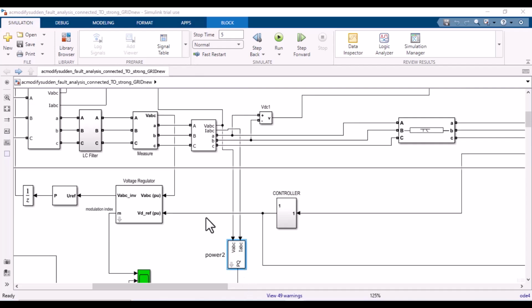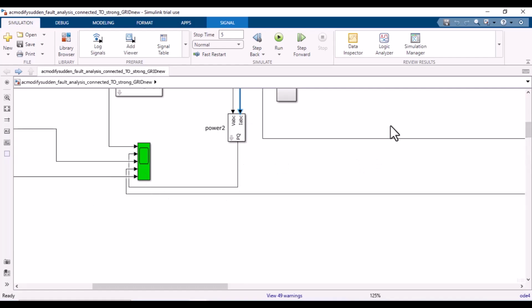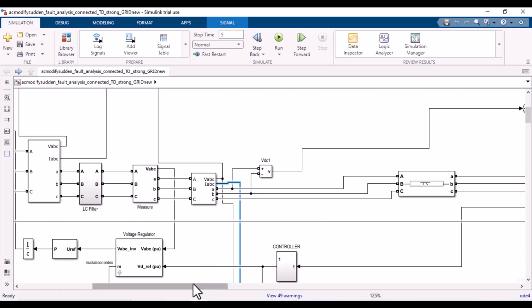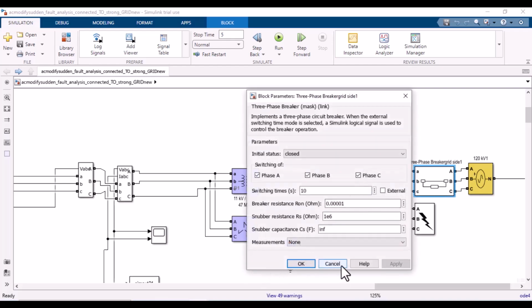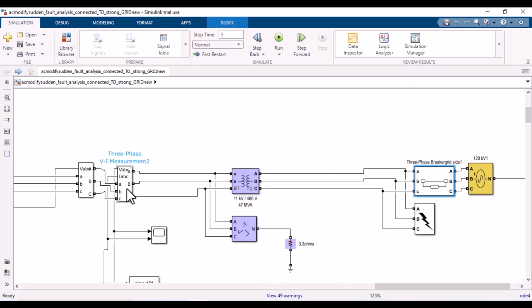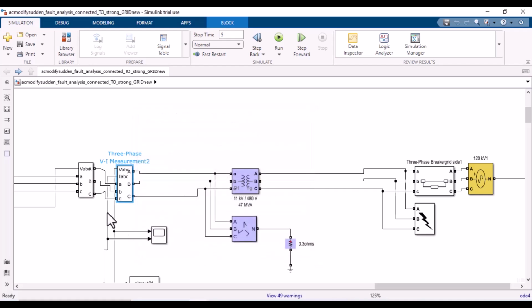It is the third waveform on the same scope. This one is the power block; it's reading the voltage signal and the current signals. This is in three phase, so these three-phase signals are voltage and current waveforms. Its output is PQ, meaning the real and reactive power. We will get the real and reactive power of these signals. The voltage is coming from the output of the LC filter and the current of the output filter, and we can run these using the scope. We can obtain the pulses using the scope.